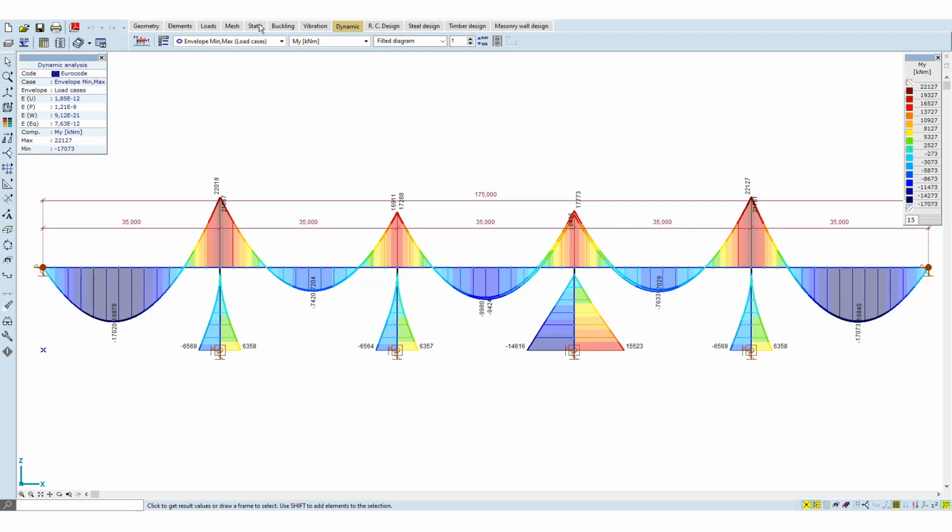We can quickly compare the two by swapping between the static and dynamic tabs. The nonlinear time history analysis considers the real plastic hysteretic behavior and energy absorption of the isolator and leads to more favorable results. Nonetheless, the iterative response spectrum analysis using isolator elements in AxisVM can provide reliable and conservative results